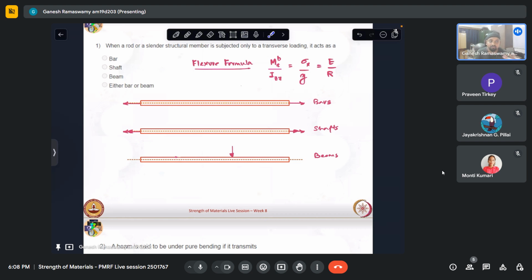When it becomes a multiplanar problem, that is, bending moments act about multiple planes, then we will simply use linear superposition and superimpose the results in order to get what we want, which will also come under the purview of unsymmetrical bending, which we will study later. But the basic stepping stone of this happens to be the bending formula, which in its simplest form is this.